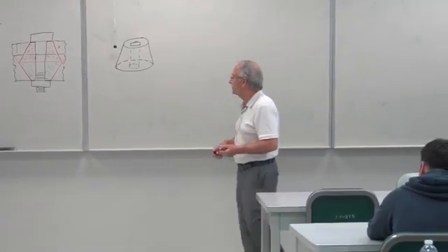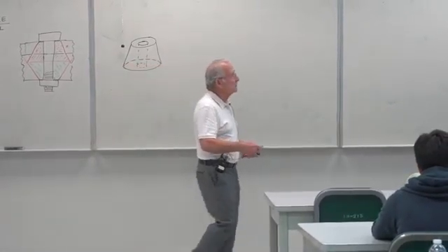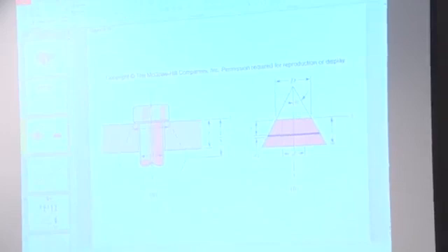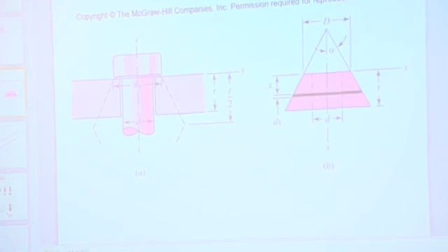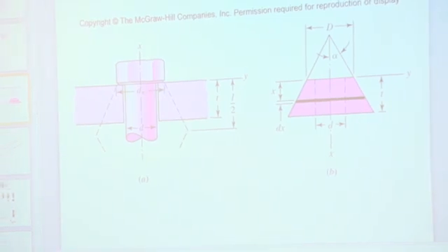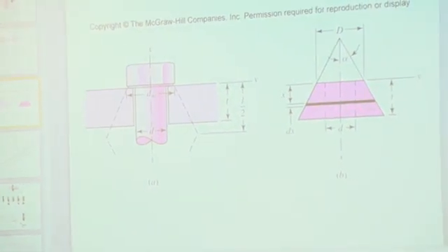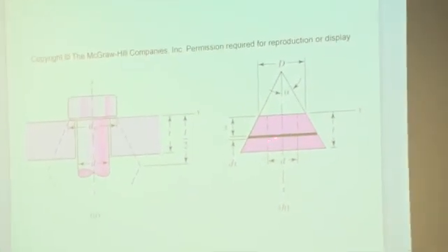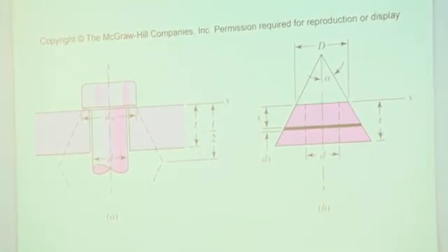So here's what we do. And for that, I'll just refer you to the screen. So here's the frustum in 2 dimensions. This angle alpha is, depending on whose book you read, a little bit different, but it's close to 30 degrees. Your book actually uses 30 degrees. So since the area is changing here, we can't use that equation. But if I take a small element here, dx, I can use that equation.